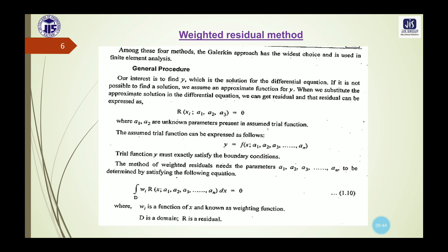Now among the 4 different weighted residual methods, the last one, that is the Galerkin method, is actually used in the finite element analysis. Now what is the general procedure for this weighted residual method? In all these weighted residual methods, we need to find the value of y, which is actually the solution of the differential equation, which will be given in the numerical.